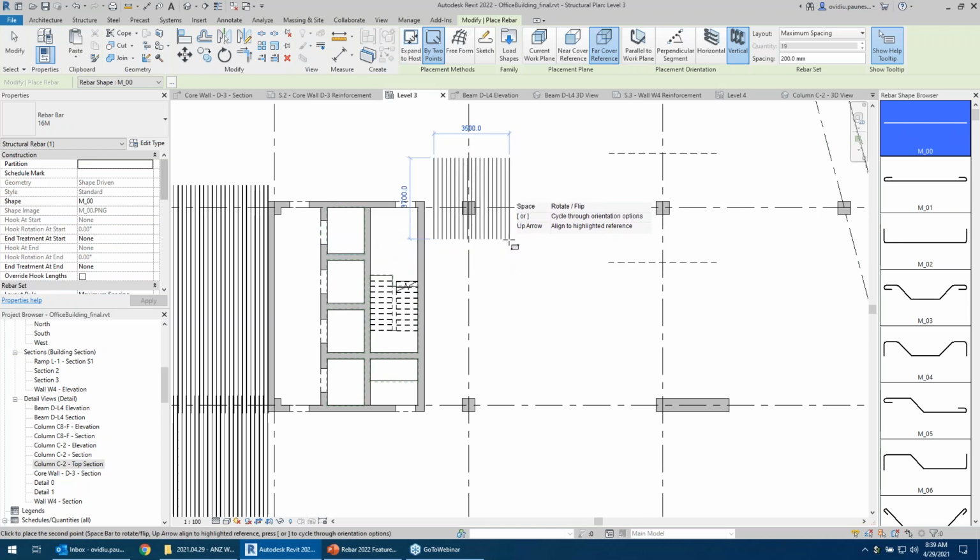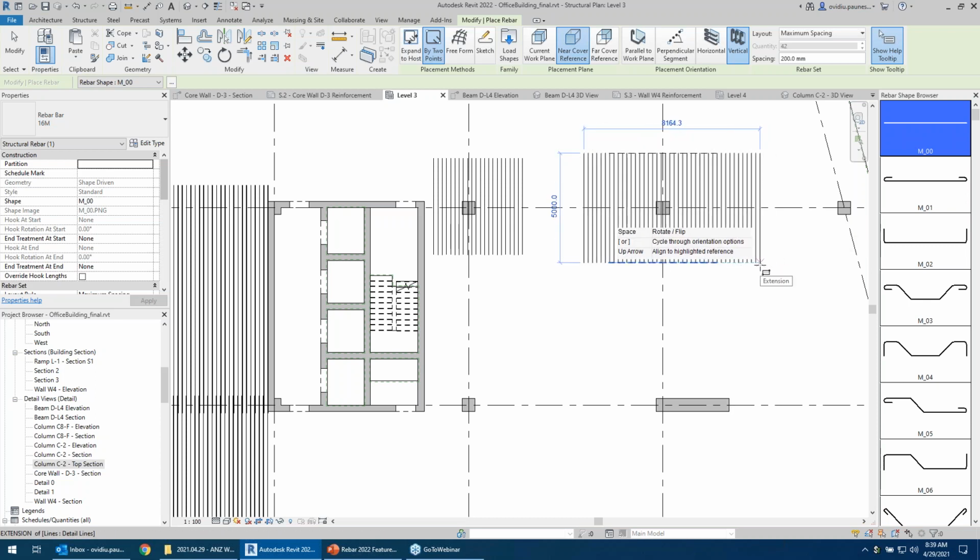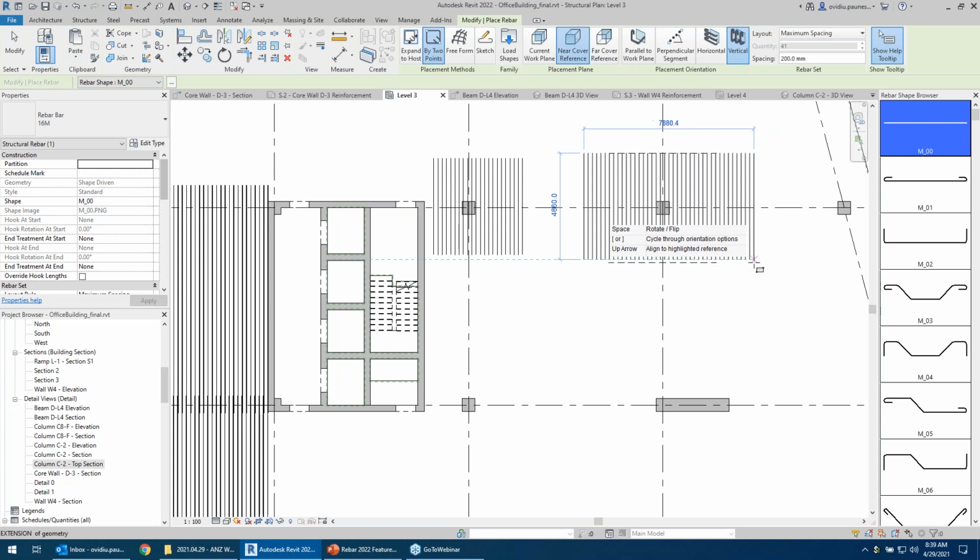If it's snapping, it's snapping precisely. If it's not snapping to an extension, I can choose the length of the bars and the length of the set by the snapping options that I have set in Revit. Okay, if I have other references in my project, I can, by the way, this is the top reinforcement, I can snap to those in extension and place my set.